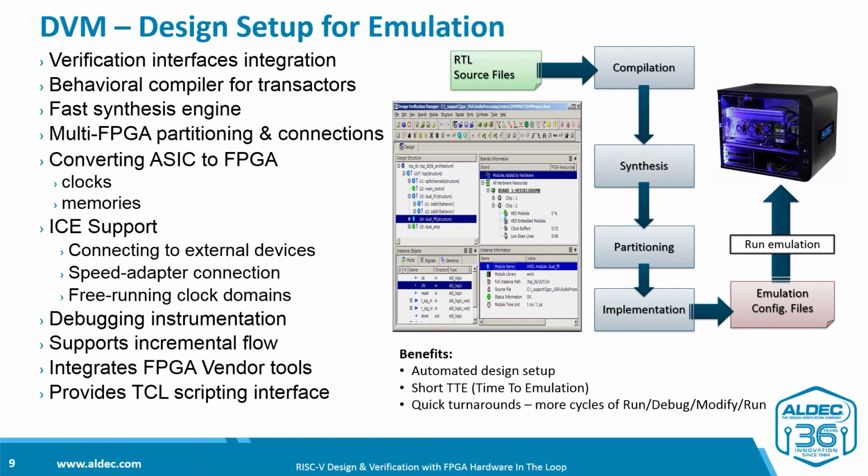If you plan for in-circuit emulation, ICE, it requires connection to free-running clocks or external devices. DVM facilitates connection of such modules too. Important part of emulation is hardware debugging. During design setup, DVM tool provides source code instrumentation to preserve all required design internal signals and integrates the design with debugging infrastructure.